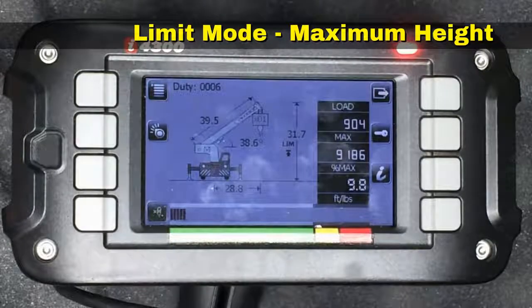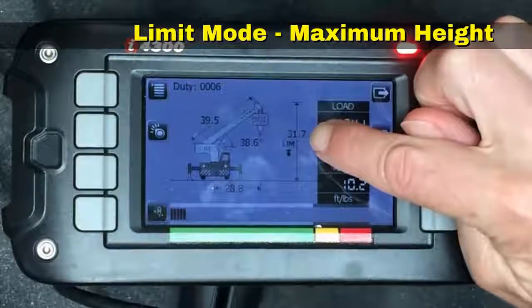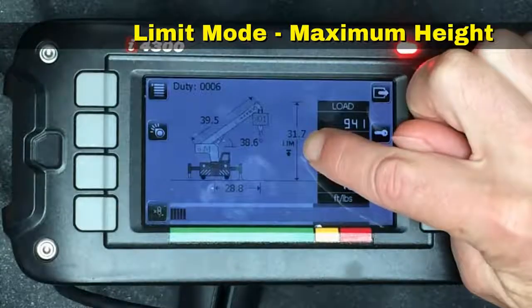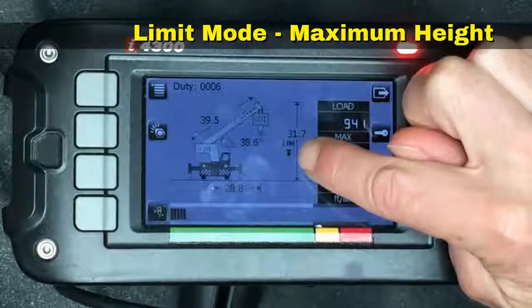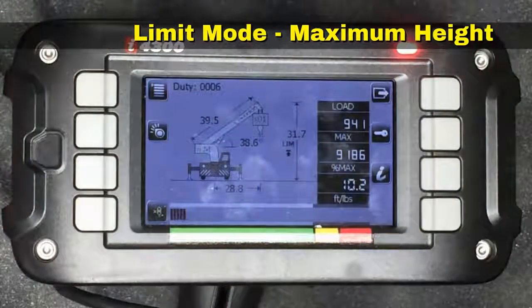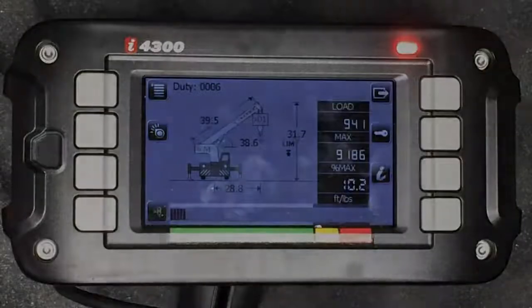So now the tip height is 31 feet above the ground. We had a maximum tip height of 30, and it had gone into an alarm condition. Again, you see the tip height above the ground here, the LIM indication, indicating that a limit is turned on for this variable, and the arrow pointing upwards indicates that we have hit or exceeded the upper limit.